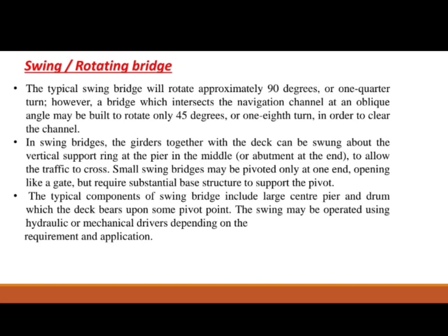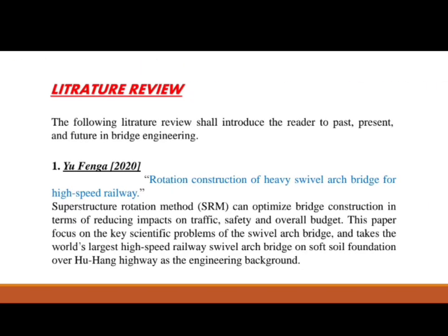Small swing bridges may be pivoted only at one end, opening like a gate, but require a substantial base structure to support the pivot. The typical components of a swing bridge include the large center pier and drum which the deck bears upon at some pivot point. The swing may be operated using hydraulic or mechanical drivers depending upon the requirement and the applications.